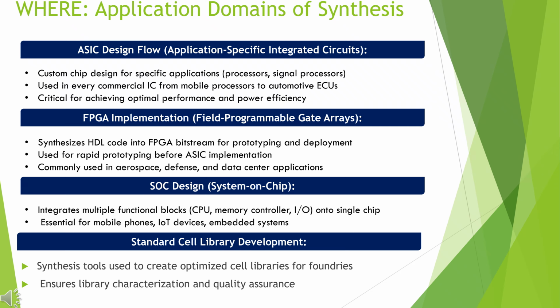Correct. In FPGA flows, synthesis converts your HDL into logic that can be mapped onto lookup tables, flip-flops, block RAMs, and DSP blocks inside the FPGA fabric. And in SoC design, we have many blocks, each synthesized separately and then all brought together on one chip. Exactly. Library teams also use synthesis-style flows for building and validating optimized standard cell libraries for different process nodes.